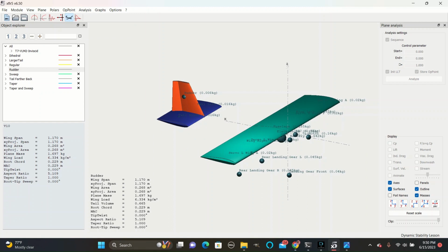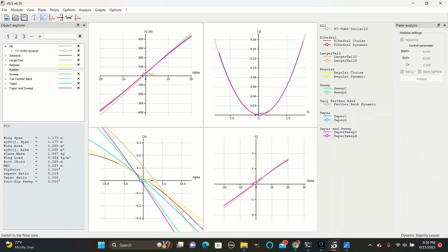Induced drag is drag from producing the plane's lift. This is what the CD graphs here in XFLR will refer to. It is induced drag. Parasitic drag is the drag from the plane's cross-sectional area forcing against the air. This coefficient is added to induced drag to get the total drag.